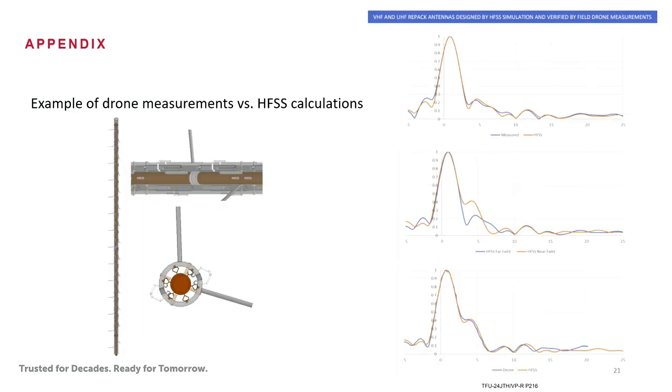It also works in the elevation pattern, not only in the azimuth. And this is where it's particularly interesting, because getting into the far field on elevation is tough if you're doing a drone, right? You've got to be a half a mile or more away to get into far field on your elevation pattern. So typically when the drone is flying that circle within 400 feet of your structure, you don't need to have an FAA waiver to do that, okay?